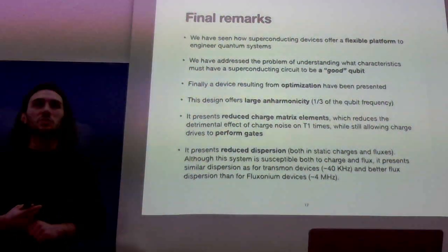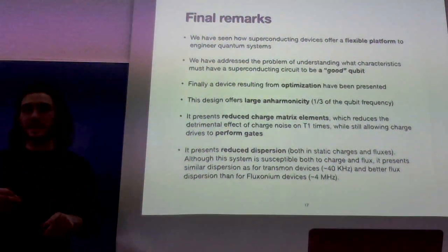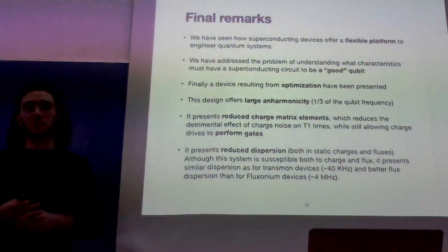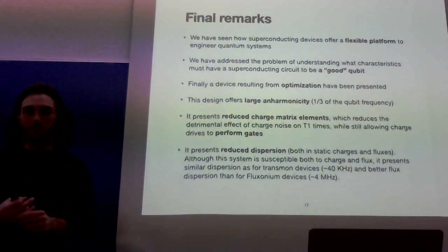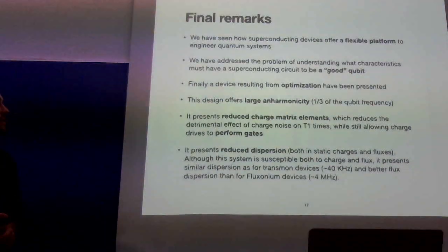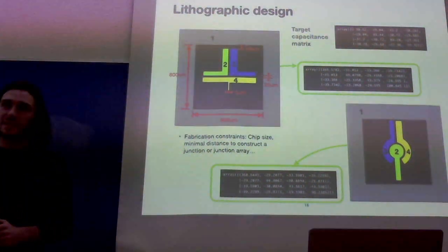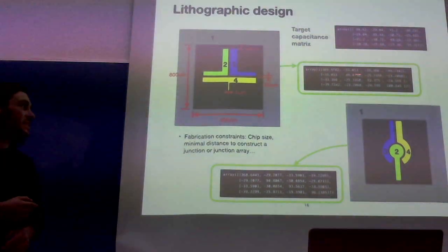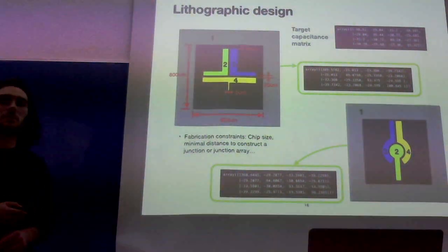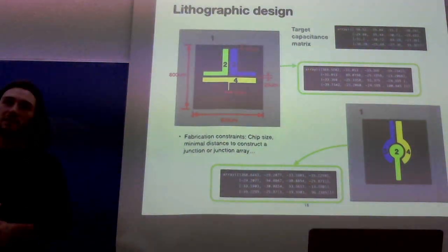But if you want to have four islands inside there, the capacitance you can reach between every island is like 30 femtofarads. So you have to compute capacitance energies from these layouts to see what are the real parameters that you can achieve, and then use these capacitances that you can reach, put them into the first optimizer and optimize the theoretical description.